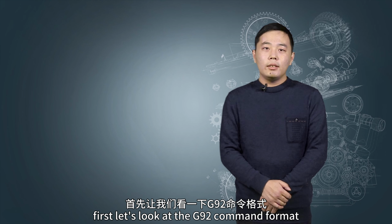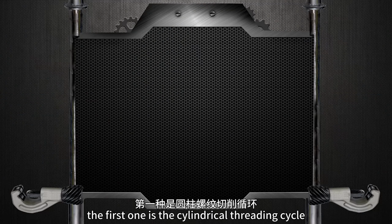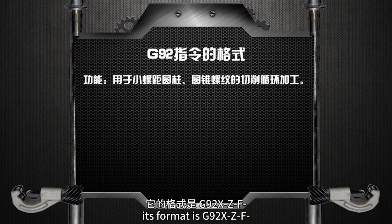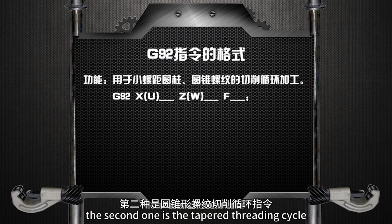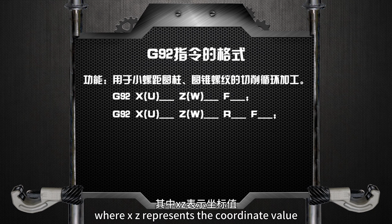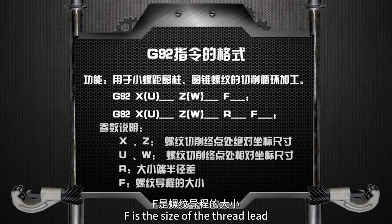First, let's look at the G92 command format. G92 has two formats depending on thread type. The first one is the cylindrical threading cycle. Its format is G92 X Z F. The second one is the tapered threading cycle. Its format is G92 X Z R F, where X, Z represents the coordinate value at the end of thread cutting. F is the size of the thread lead.